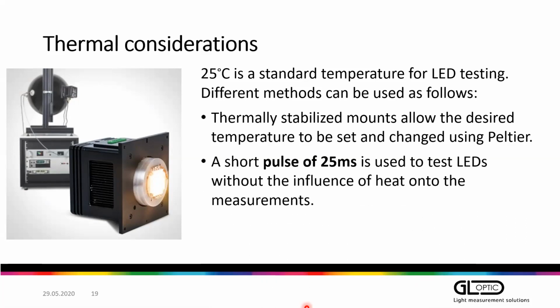There is another method very popular in the production of LEDs, which is a short pulse of 25 milliseconds. And it is assumed that in such a short pulse, there will be no influence on the parameters, on the performance of LEDs, because they will not heat up. At least if everyone is using the same pulse, and then the measurements are comparable.